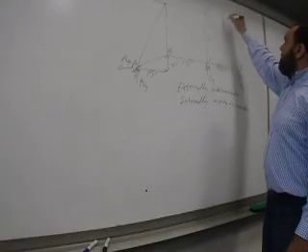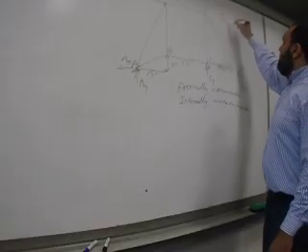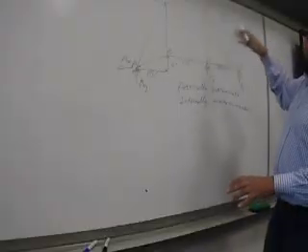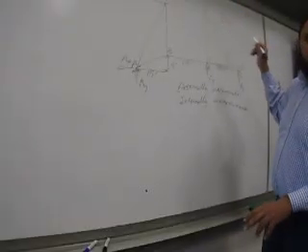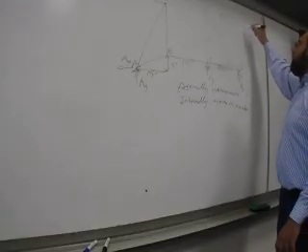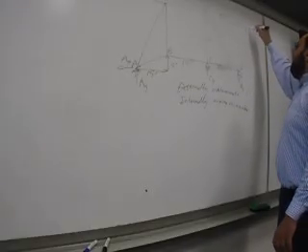But how do we do the determinacy thing? I need an additional equation. Globally, I have sigma Fx equals 0, sigma Fy equals 0, sigma M equals 0. The easiest thing here is to start with the sigma Fx of the whole structure. I'll solve the whole structure in black. The sections will be in the other colors. So for the whole structure, sigma Fx equals 0, so I have 60 kilonewtons minus AX.